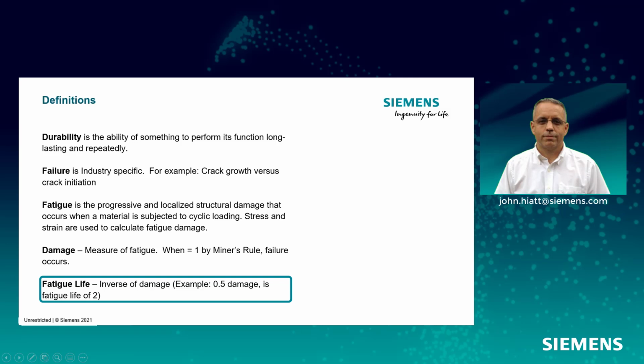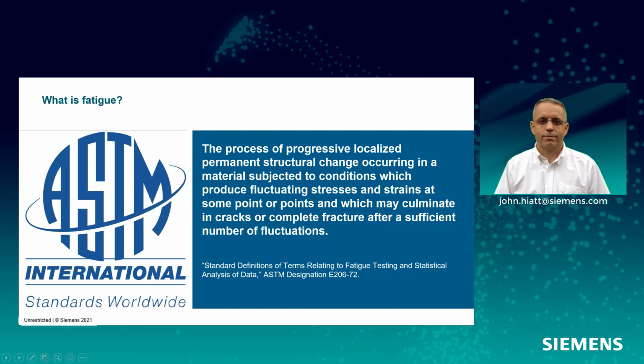Some people will use damage as a metric. I've seen people use hours as a metric. I've seen people use kilometers as a metric, how far you can drive. But typically it's just taking damage and normalizing it, or calculating how many repeats of a loading environment, and then you can get to a total hours. So damage and life, and we'll go over in detail how to calculate damage. Here, just for your records, is the official definition of fatigue according to the international standard.